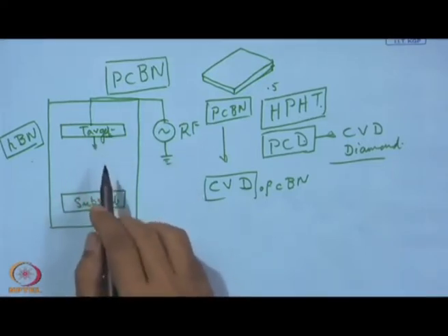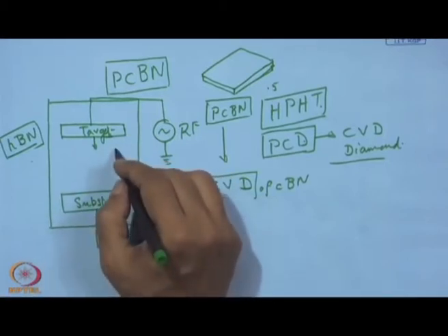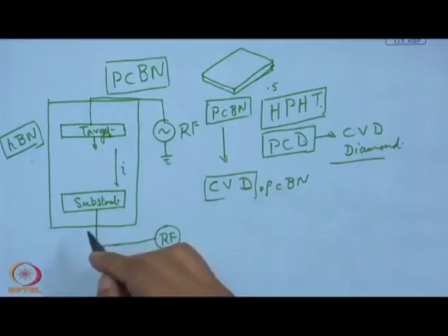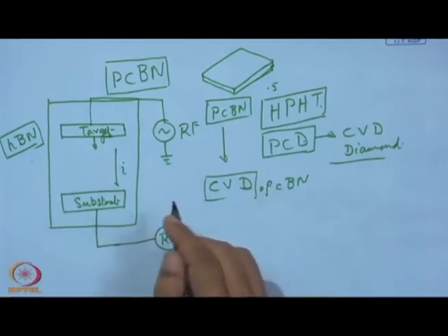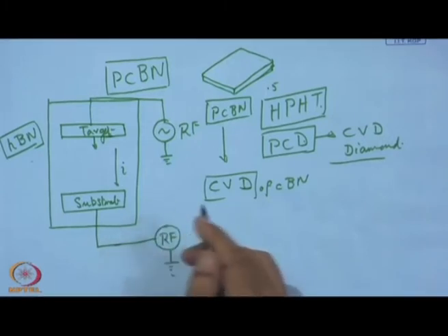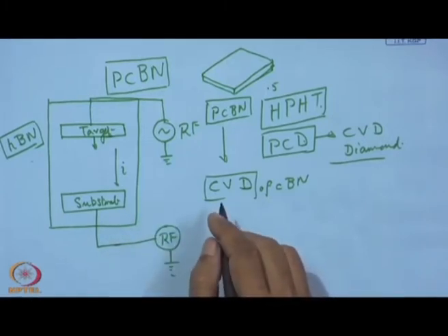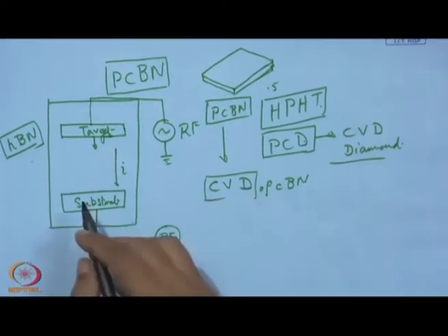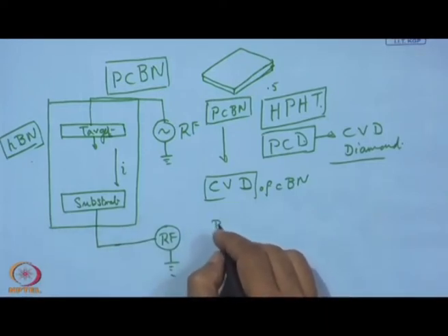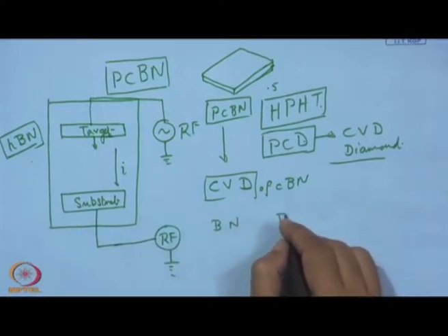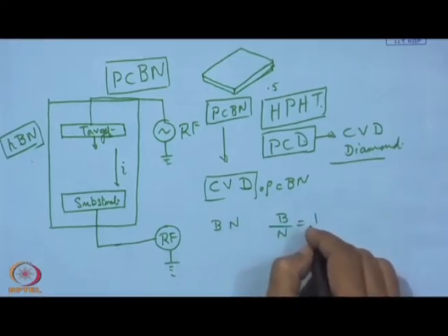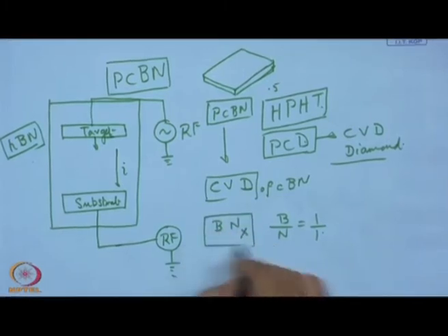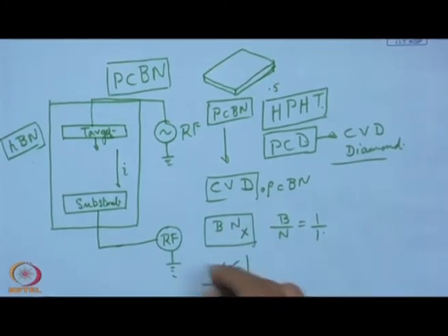However, sputtering is possible, and by this ion impingement, by this ion bombardment towards the substrate, which is also negatively polarized, it was possible to have some sort of cubic formation, but it was not a total success. More importantly, the main problem was that it was no more B to N as 1:1, but less than 1. So, it is actually BNx, where x is less than 1.